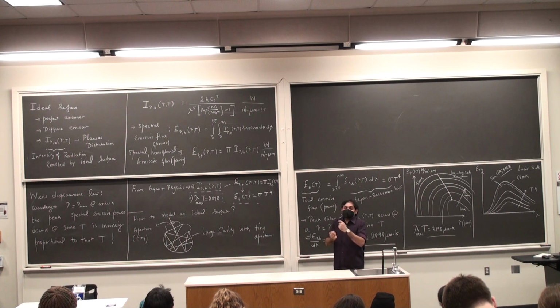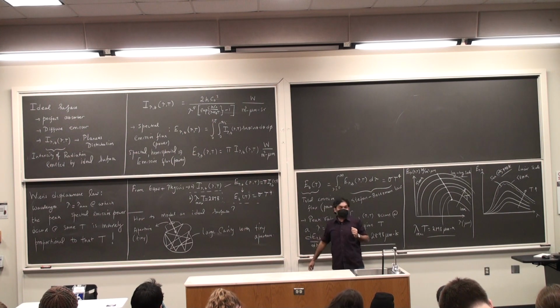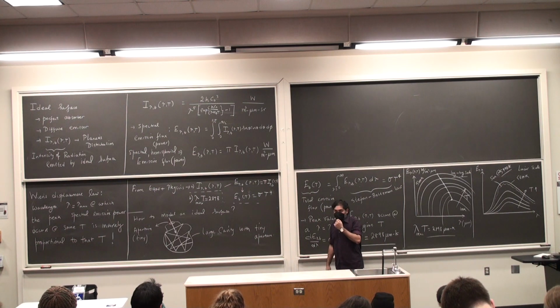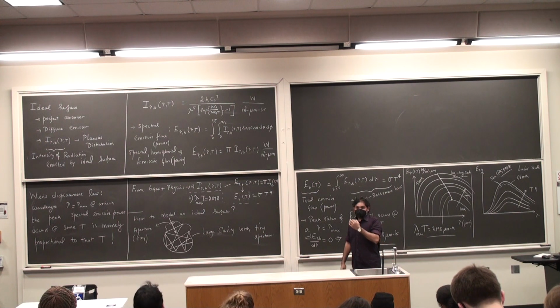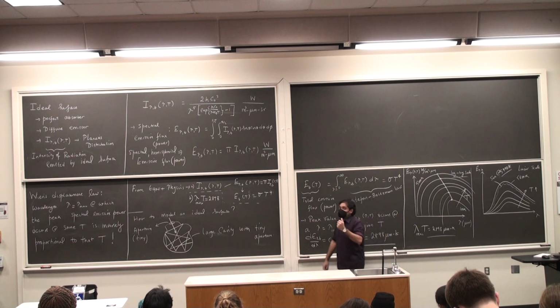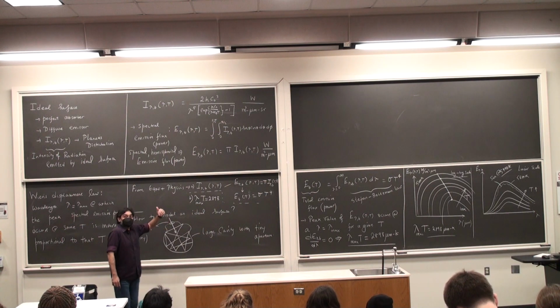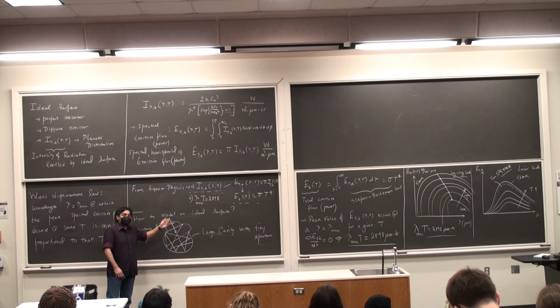And so what this means is that this aperture is acting as an ideal surface because whatever radiant energy is incident on it is absorbed completely. You see the technicality here. It's not the cavity that's the ideal surface, it's the aperture that's the ideal surface. So whatever radiant energy is incident on it is completely absorbed by it, because this radiant ray that is passing through the aperture has a very little chance of escaping out. It is just going to keep bouncing off the walls of this cavity.